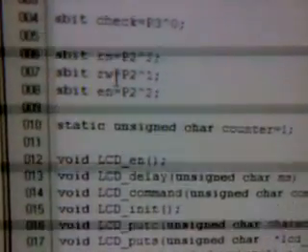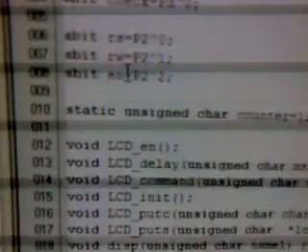This is reg51, which is the 8051 library header file, and then I am assigning the single bit ports, port 3 bit 0, and the RS pin, RW pin and enable. And this is the program, which is just 112 lines. The program is very simple, written in embedded C in the Keil compiler.